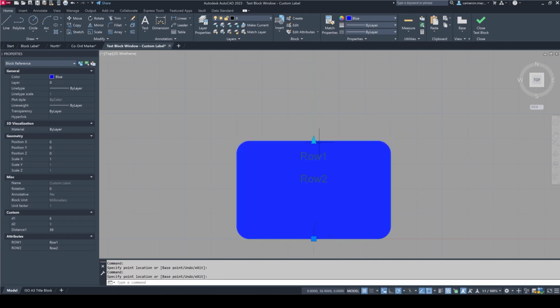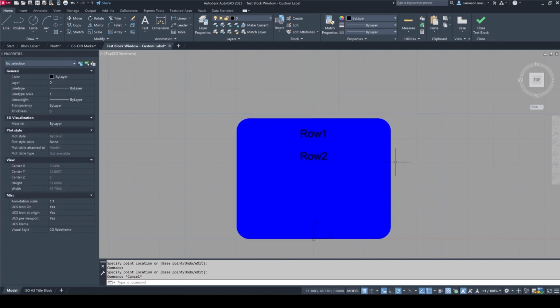Interesting. Okay, there must be something ever so slightly wrong with that parameter, but you can see it is still working. It's still keeping that gap exactly as we want it to. So for the most part, that's working. It might need some minor tweaking to the configuration of those parameters over there. But if you aren't wanting this to adjust, and you're just wanting a single static 3-row block or 3-row label, you can essentially repeat the same process, but ignore the whole stretch and list parameters essentially from inside of that.